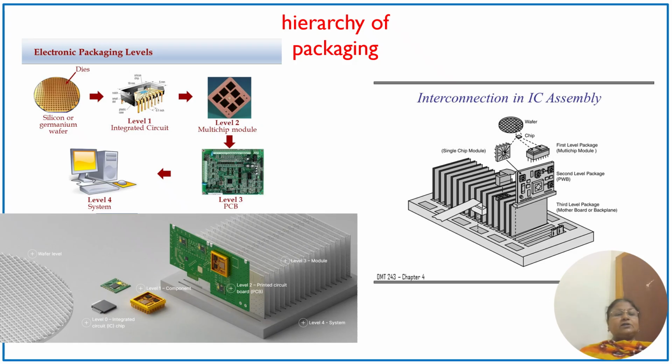And after that, this silicon wafer has to be taken to an IC design process. Each die is utilized for this activity, and an integrated circuit is going to be fabricated. So this is a well-known process, by a monolithic IC process. We can go over the steps, starting from the silicon wafer, where on the wafer you have oxidation, deposition, diffusion, ion implantation, doping.